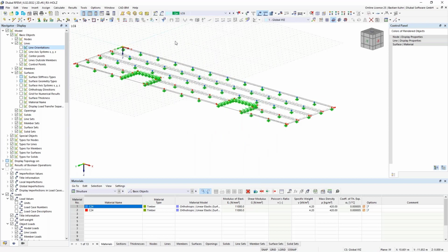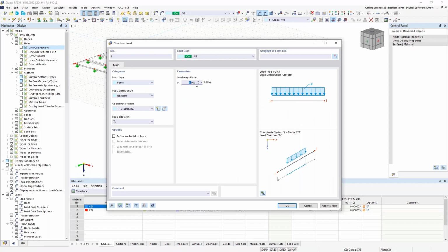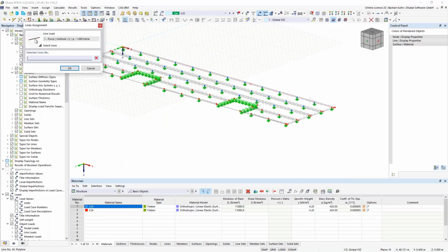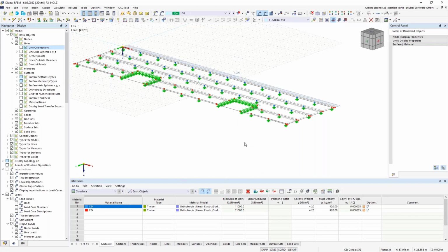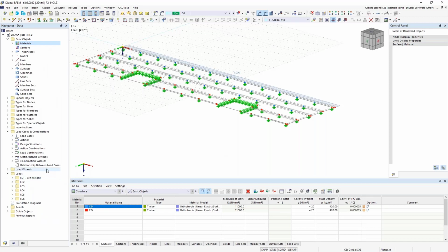And in the load case 6, we can, if we want to, define a line load with a value, I don't know honestly, load direction, we take 1 kilonewton per meter and take the y direction, and then say okay here on the outer line, okay, and then it's there. So that works the same as in RFEM 5. That was the old traditional way. So we did both options. Okay, now combination, and we can do the or start the analyzing or design process.